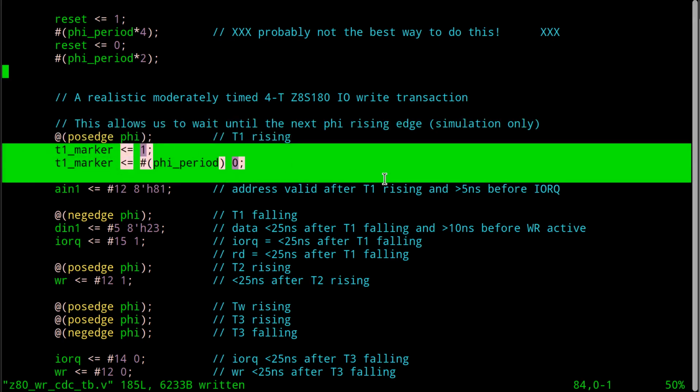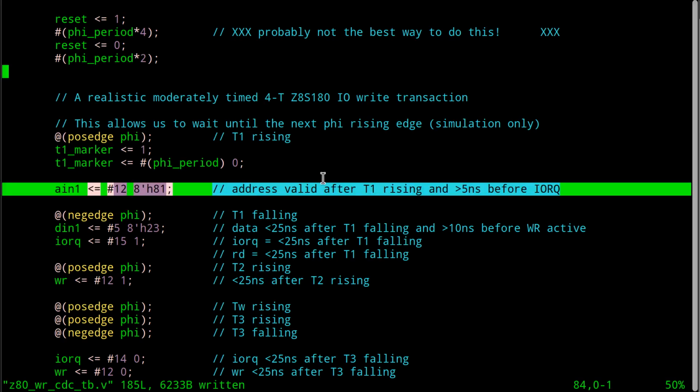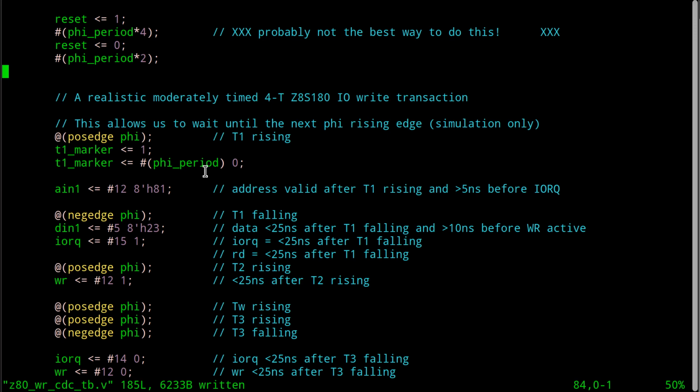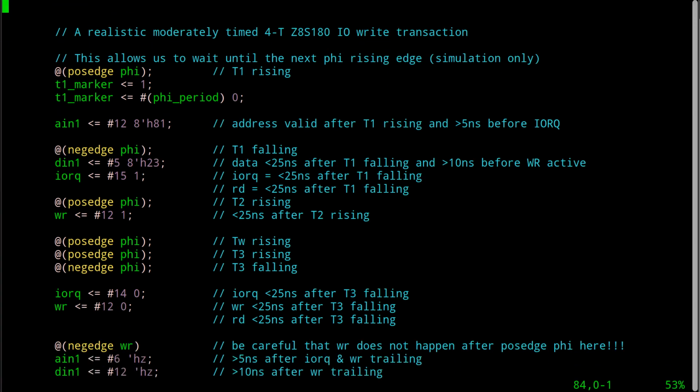So let's look and see how this marker works and what's going on here. Now, this is just Verilog, okay? And we've talked about this before, but here's an application that, if you hadn't thought about it for a while, it obviously only works for simulation because these delays do not apply in any way, shape, or form to synthesized code, okay? So, and I don't give a lot of thought to simulation. I always think about the synthesis. And so sometimes I'm lazy and I don't really reason this out.